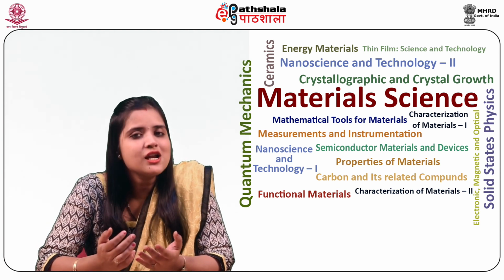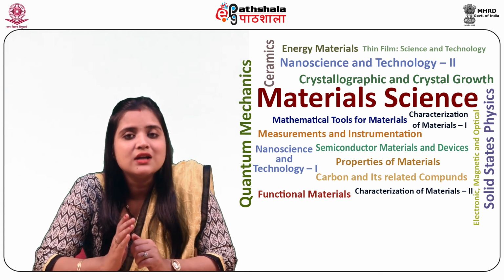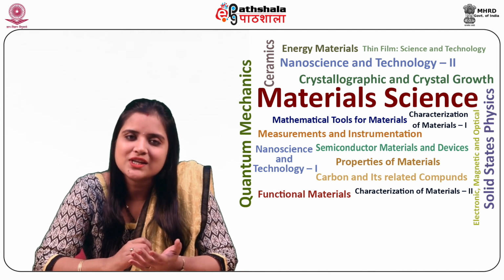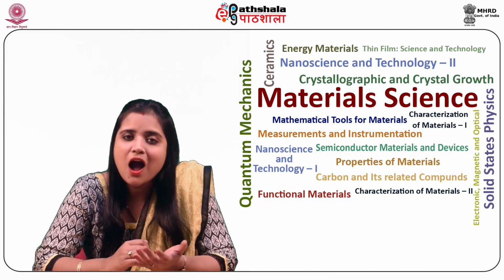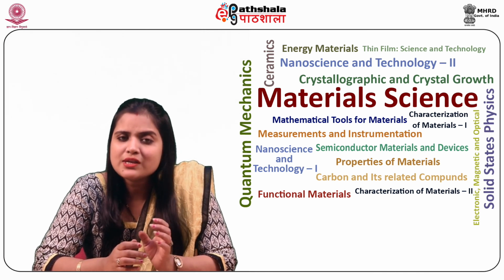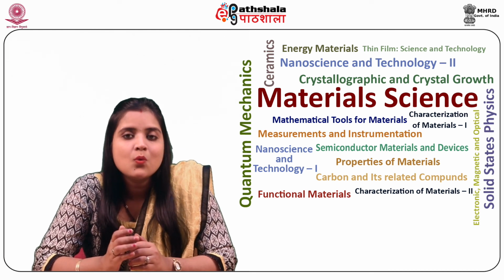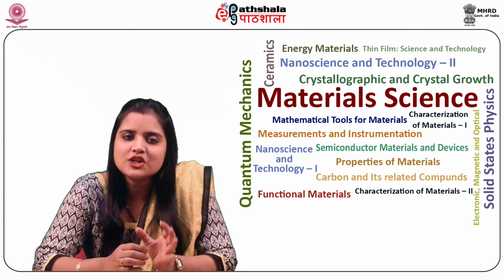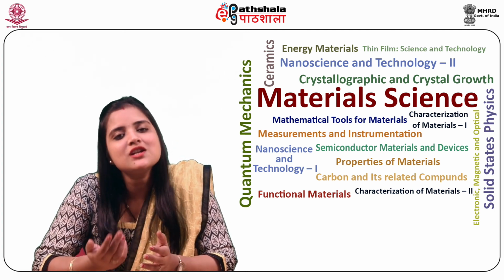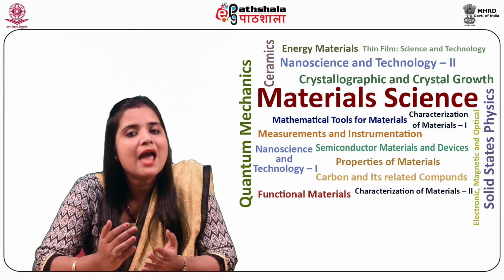Basically, single crystal ferromagnetic materials possess directional magnetization properties, that is, easy and hard directions of magnetization. This is attributed to the energy which is needed to magnetize a material in the direction of the externally applied field with respect to the crystal axis.